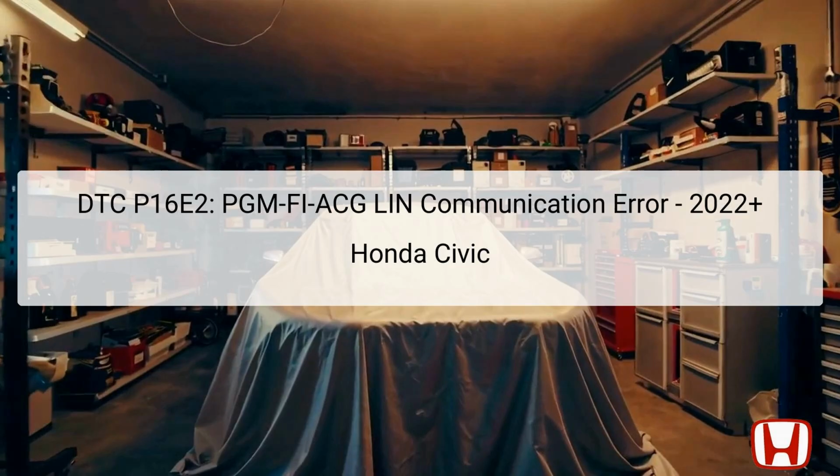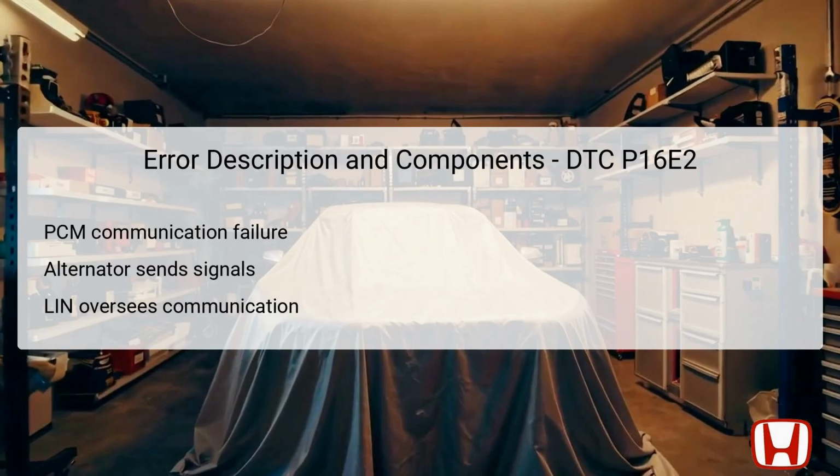Before proceeding with the diagnostic process, it is essential to review relevant manuals and potential causes for this issue in detail. DTC P16E2 signifies a communication failure between the alternator and the PCM due to issues within the LIN circuit. The PCM monitors the performance and function of the alternator by receiving signals pertaining to voltage and operational status through the LIN. Any disruption in these signals indicates a failure in communication.